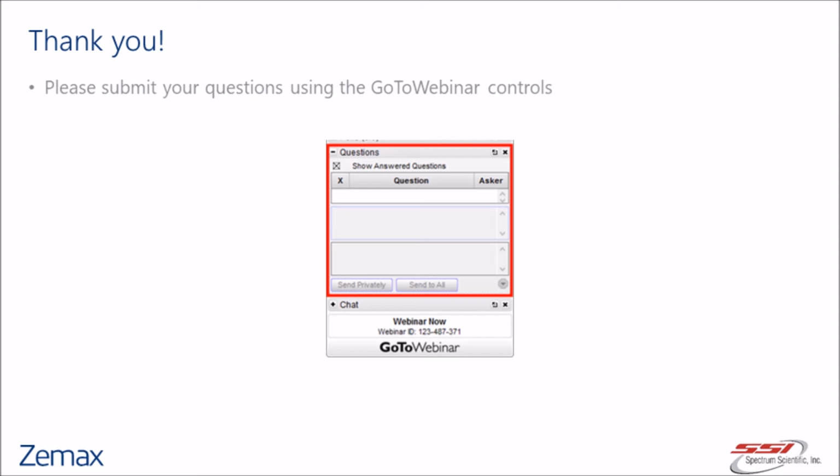I usually do that with ray-based calculations. So the focal length is related to the shift of the chief ray on the image plane. So it's fairly straightforward to use ray data to set that up in your merit function.